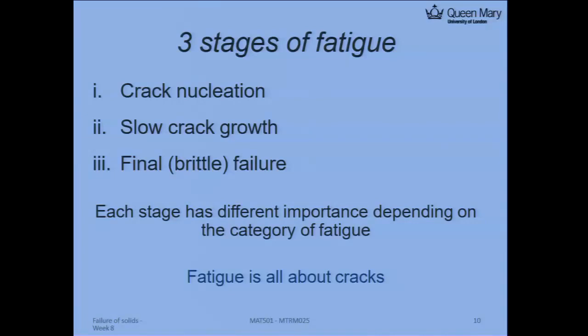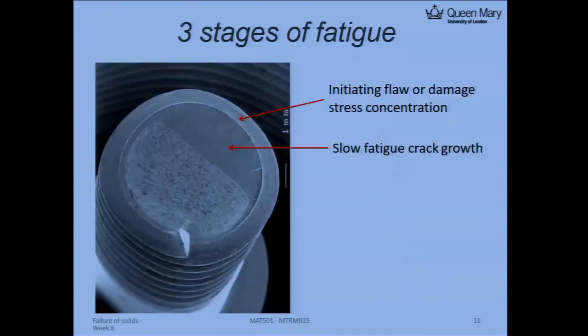So in this part, we first of all look at the crack nucleation. But before I do that, let's just look at the typical failure, which I have shown you in the first introduction. This is for a bolt from your bicycle, actually, probably behind, just on the bottom of the seat. If you look at the fracture surface, there is an initiation at